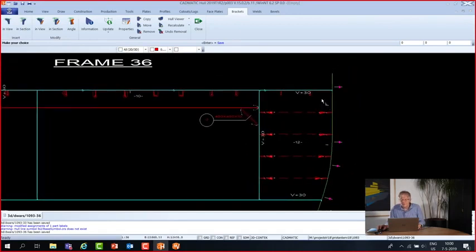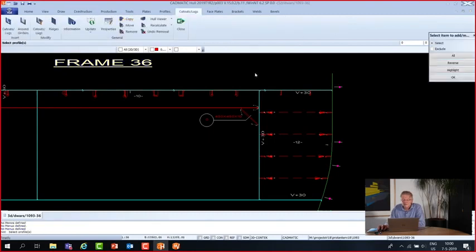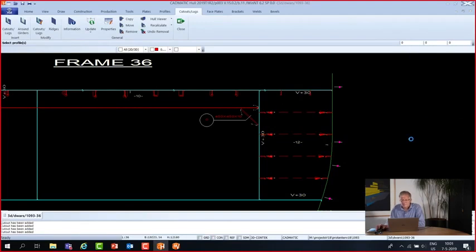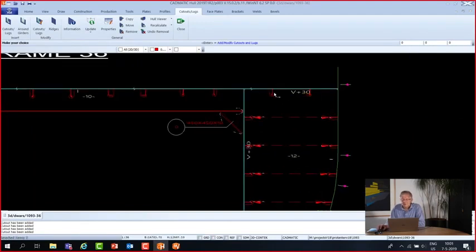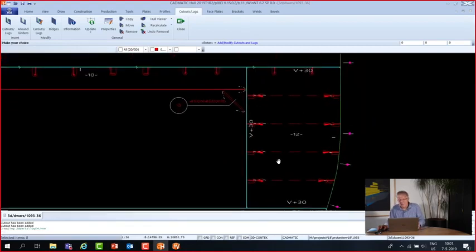Some cutouts need to be added because this is now a watertight bulkhead, but it should be an open bulkhead. So cutouts are needed. Yeah. And we see all the openings. But these small openings are not enough to get all the ballast water or fuel, I don't know what will be inside the tank. There need to be bigger openings, and those I will now show you.